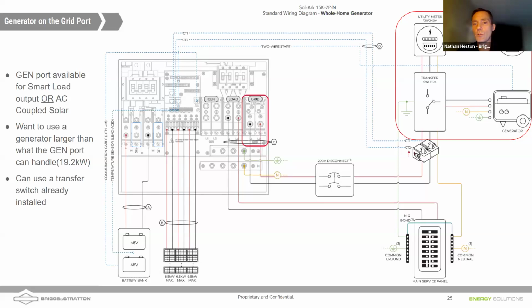Now that load management is based on what, Daniel? Power. Yes, power, right? So the load management modules that you'll get with our transfer switches will come on and off based on how much power is being pulled from the generator. Now, if you've got a slightly undersized generator and you're worried that large loads, in addition to battery charging, are going to take you over your power limit, having control modules that will drop off big loads like the air conditioner when the batteries are in a charging cycle can prevent that generator from being overloaded. So you could use load control modules there to limit how much power is being pulled.